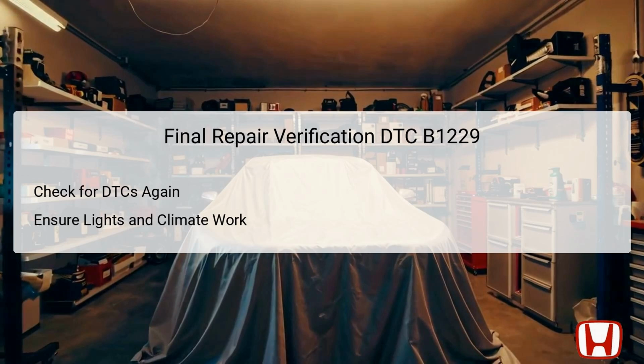successful. Start by checking for DTCs again using the Honda Diagnostic System, HDS. This step will help confirm that the diagnostic code has been cleared and does not reappear. Additionally, ensure that both the automatic lights are functioning correctly and that the climate control settings respond accurately to varying light conditions inside and outside the vehicle. This assessment is paramount in ensuring that the repair was effective and that all components are working harmoniously. If everything operates without further issues, then the repairs can be considered complete.